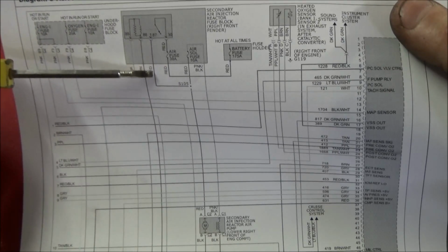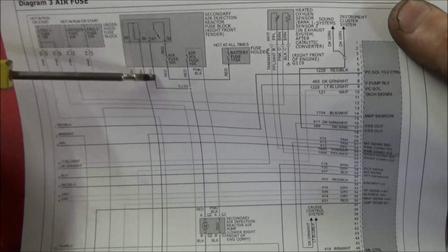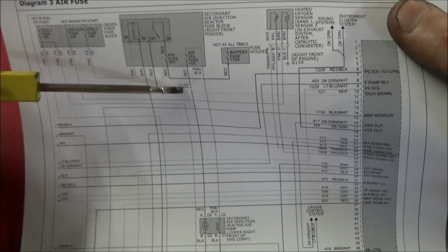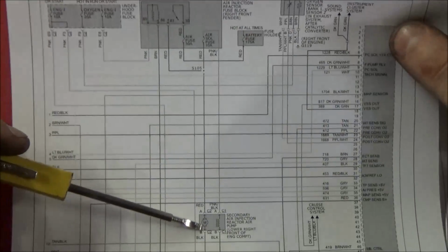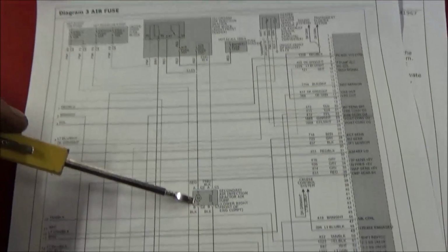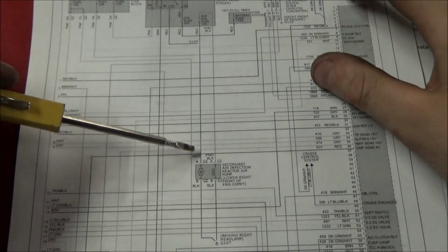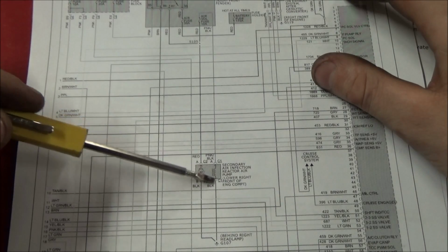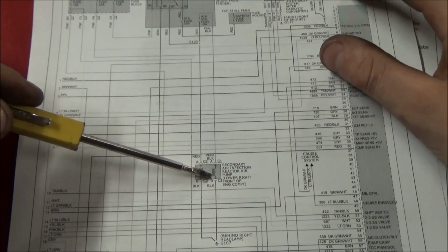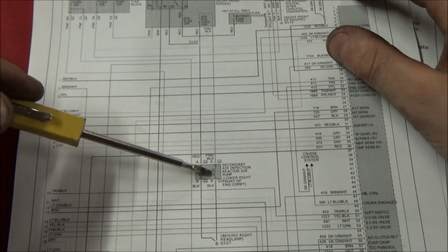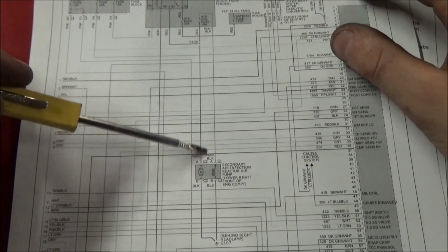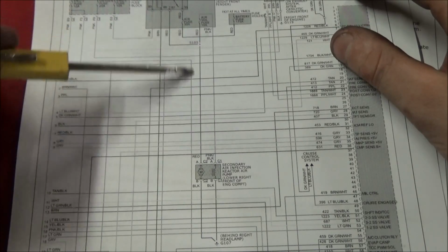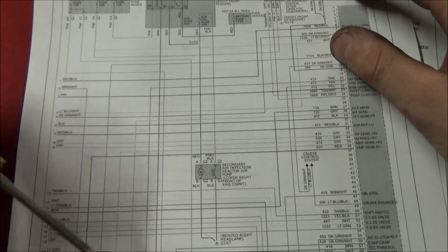So let's just follow this load side down here. It comes down here and it goes to this splice 105, and it continues going down here. And this unit right here is actually the secondary air pump motor. So we can see that the motor and what looks like the solenoid are potentially built into the same unit, based on how this is currently drawn here. But they're both controlled off of the same relay, guys, without a doubt.